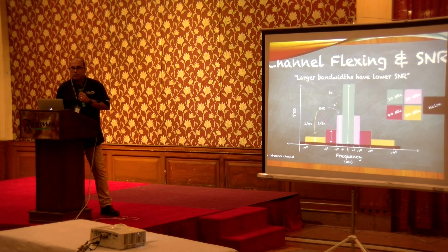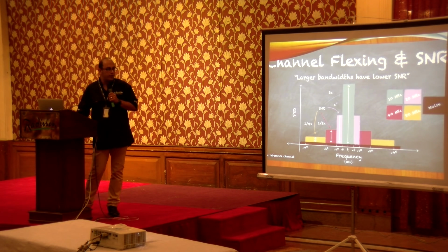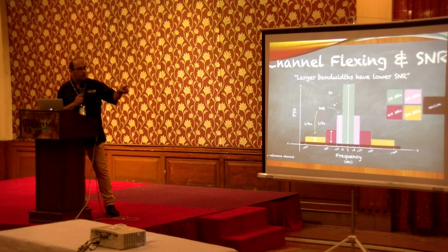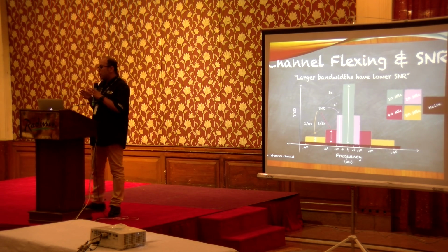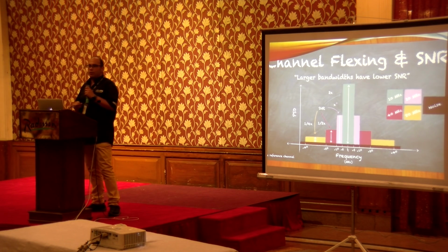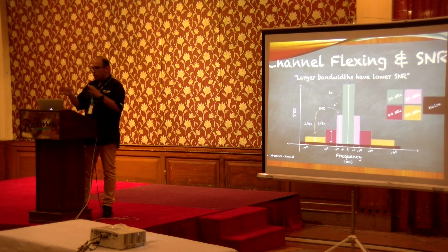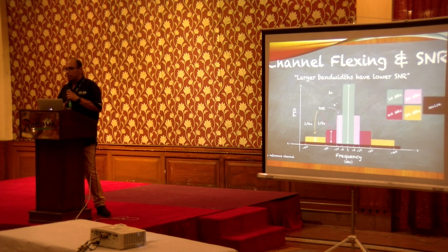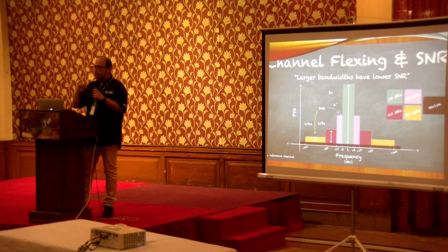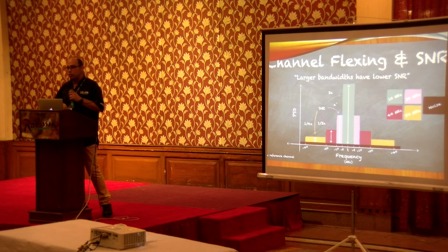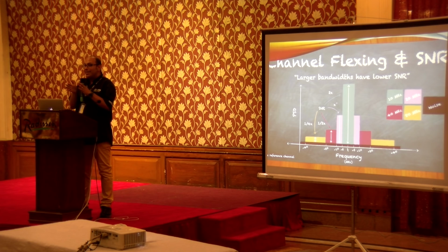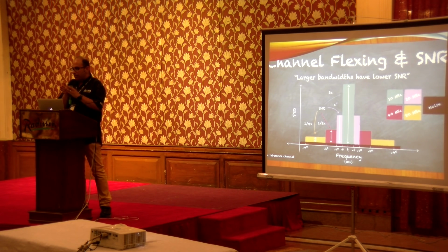This is the comparison of channel width. You know, the standard channel width is 20 megahertz. This is the standard. You still can have 5 megahertz or 10 megahertz. For example, in an installation, your channel width is 20 megahertz, but your signal is so low, because of noise or whatever. You bring down the channel width.